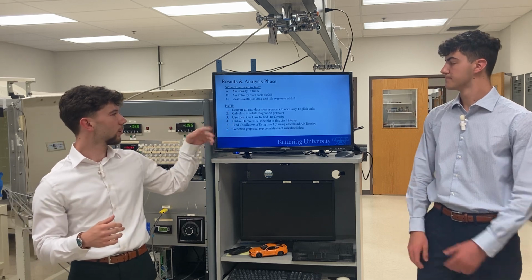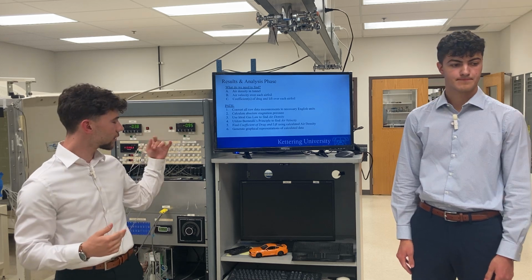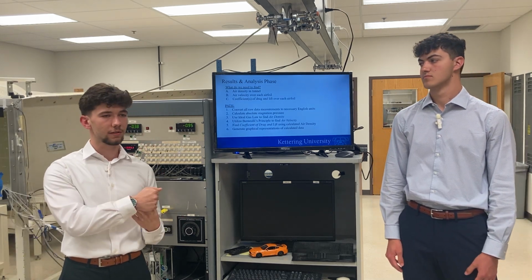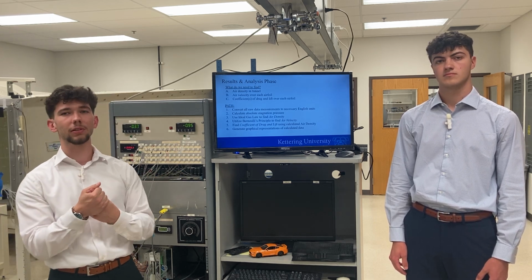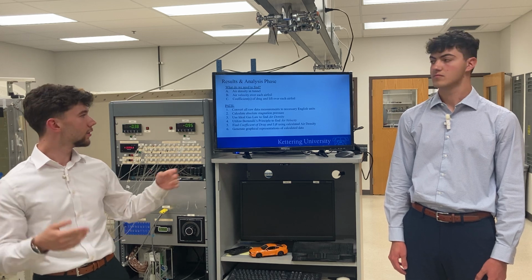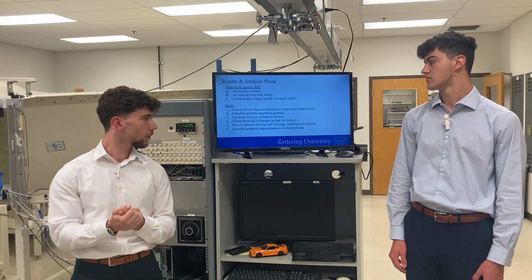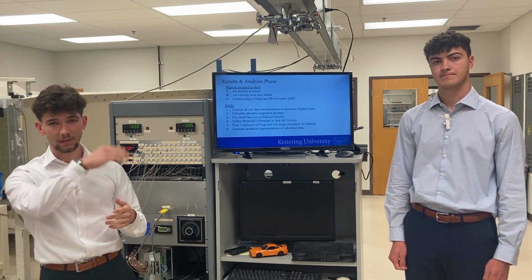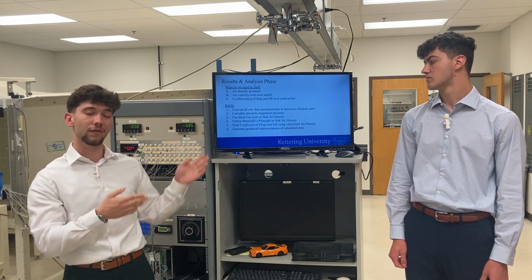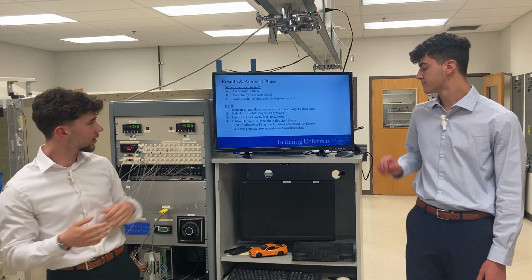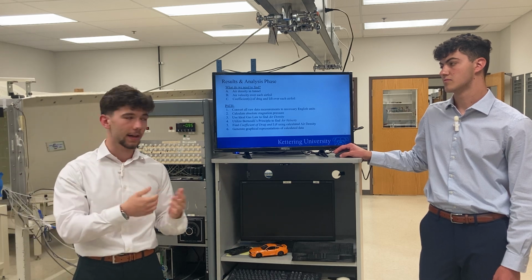Now the path to do this was first convert all of our raw data measurements that we got from the manometer as well as the digital manometer from inches of H2O into more applicable units, so PSIG for us. And then next was to calculate the absolute stagnation pressure, which is necessary to find the air density in the ideal gas law equation. Next, we had to utilize Bernoulli's principle in order to find the air velocity going over top of each of the foils. Next, find the coefficient of drag and lift using the equations from class with the air density that we calculated previously. And last, by generating graphical representations of these, we'd be able to draw conclusions from our data.